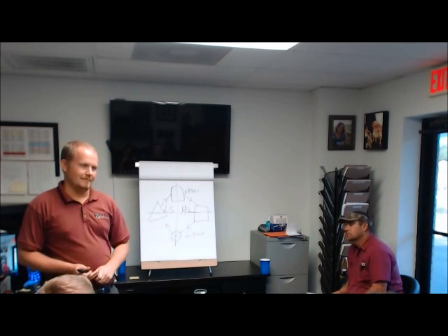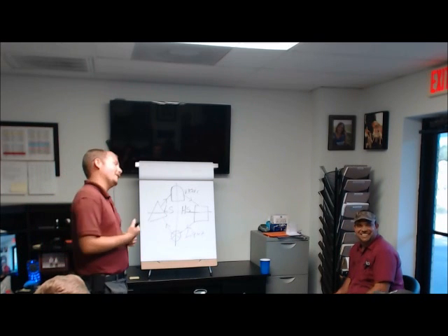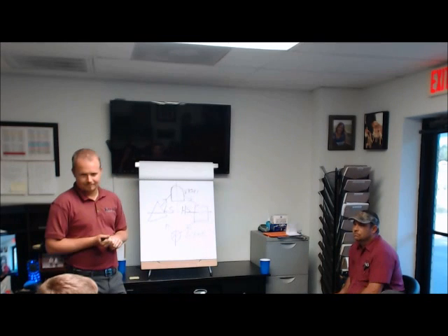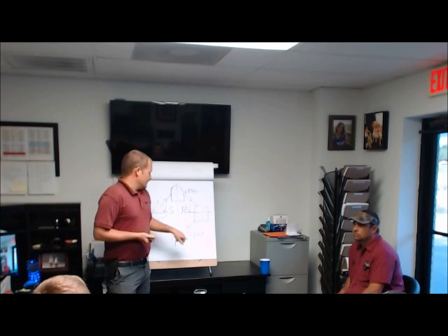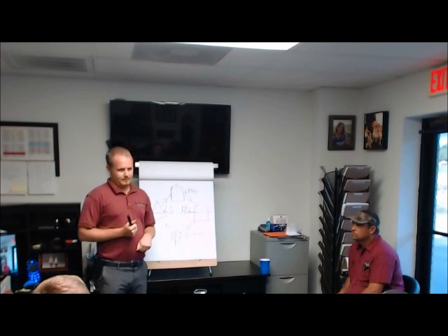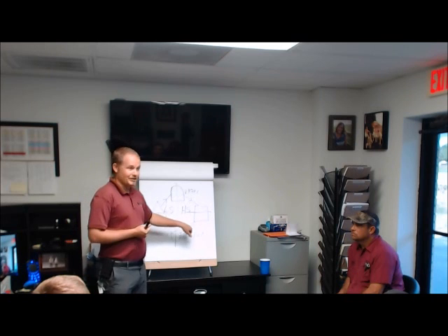That's what would make this noise. Yep. Well, that's an experienced way of knowing. I'm trying. Saturation temperature? Because pressure's low. If I read the pressure here, and I read the temperature here, right, difference, and they match at saturation.